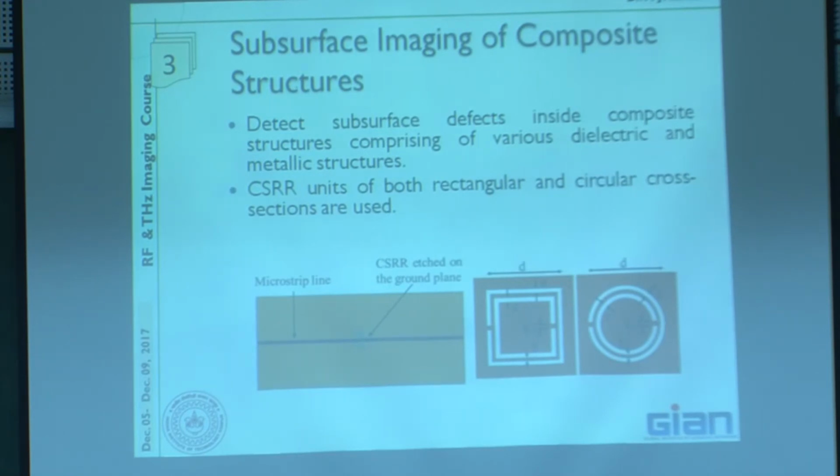In any kind of sensing, whether you have a circular resonator or some other sensor, what is the most important parameter? At the end you are measuring resonant frequency. There is something defined as sensitivity. It is a parameter which tells, for each unit change, how much change there will be in resonant frequency. There are two parameters: resonant frequency and, let's say, the permittivity. You are observing resonant frequency, and from this you want to extract the permittivity. Your objective would be that if you go from permittivity of 1 to 2, it should show maximum change in the resonant frequency.